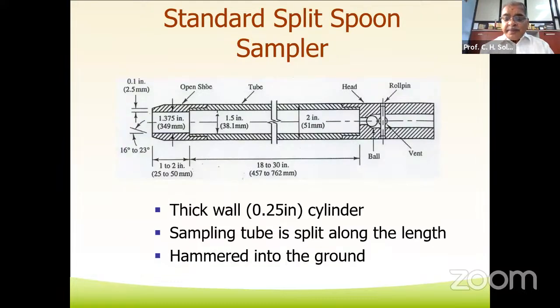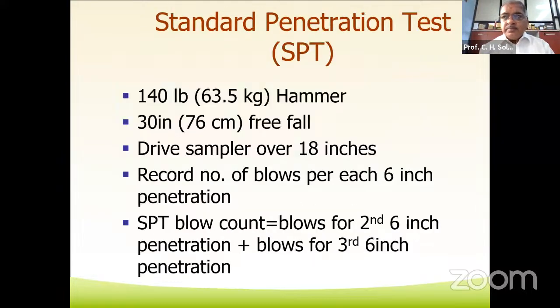We are driving the split cone sampler with the hammer into the test bore for 45 centimeters. 45 centimeters means 18 inches.